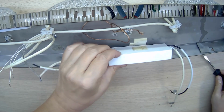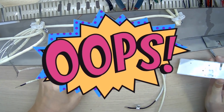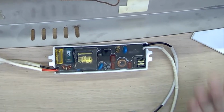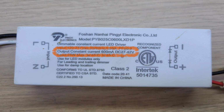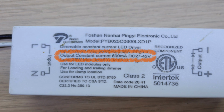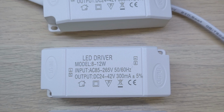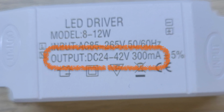Remove the driver. As soon as we remove the cover, oops! The driver is filled with compound and repair is difficult and not worthwhile. We need to find another inexpensive driver that matches these parameters: 27 to 42 volts and a current of 600 mA. The search for a completely identical driver is unsuccessful, but there is an option of 3 drivers that are not very expensive, however they all have a higher current.